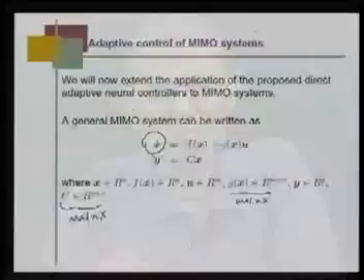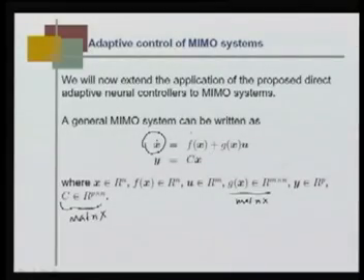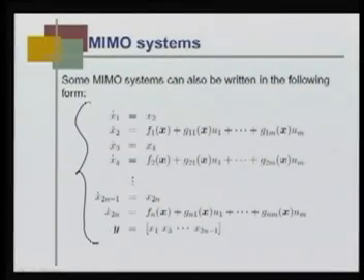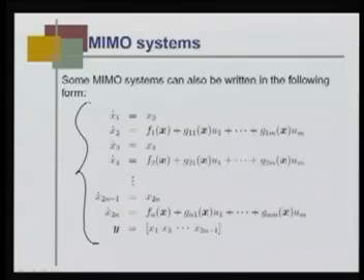So, now this is a very general form, and out of this form we will consider a very specific form, which is this one, this structure, where this MIMO system is written like this. We can write many of the system dynamics, particularly multi-link robot manipulators, all categories of multiple robot manipulator, that is 2 link or more than 2 link robot manipulator. The dynamics can be written as x1 dot is x2, x2 dot is f1(x) plus g11 u1 until g1m